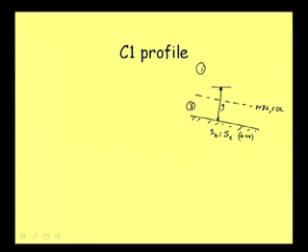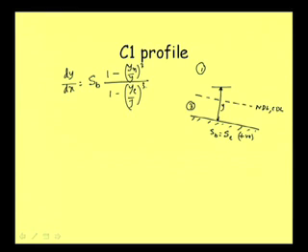Well, now again writing that expression, dy/dx is equal to SB into 1 minus (yn/y) whole cube, using Chezy's equation, and then 1 minus (yc/y) whole cube. That expression we got, the simple form of governing equation of gradually varied flow in wide rectangular channel.